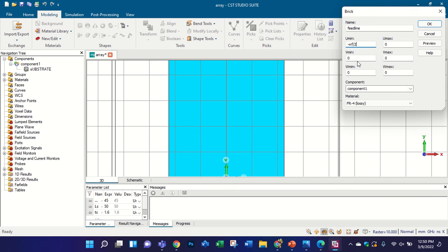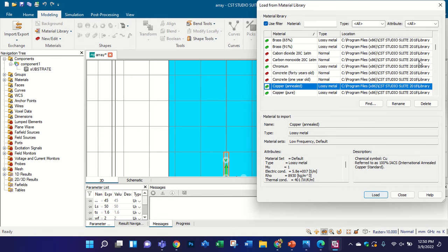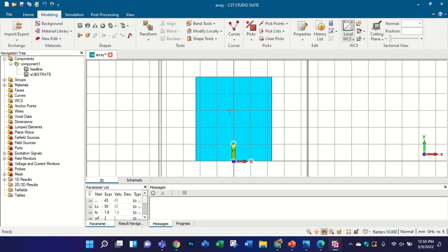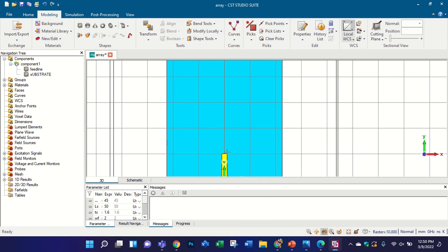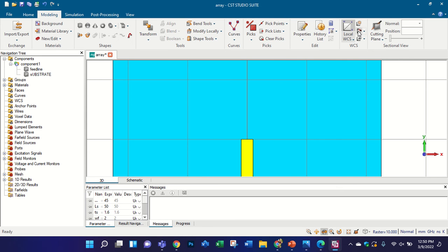Mr. Sarush and Mr. Muhammad, if you use the Chebyshev technique to get the transmission line matching, it is better for this and gives better results. Chebyshev technique for third order. Actually, we need to try it. Yes, you must get better results, because going from 15 to 100 causes more power losses. Do you know it? Because there is no intermediate transition value between 50 and 100.